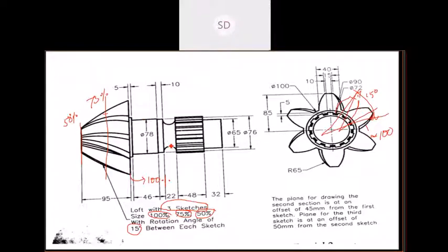Next, in some shafts, it has some groove as well as some splines over it. So now you can model this one up to this portion, okay, using the shaft option here, using the shaft feature, right? So if you draw this half section with the dimensions, you can make it in a single step. Now look at dimensions. It's 65. Outer dimension is 76. Now as this dimension is not specified, let us take this also as 65. Okay.